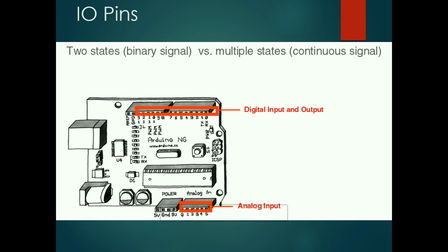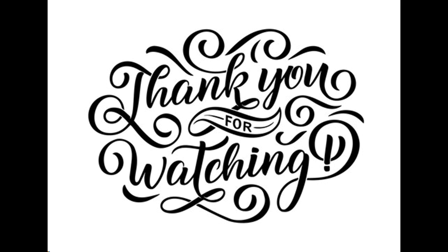Input and output pins were discussed before. Among the input and output pins, analog pins are only input. You can only give a signal as input, as analog can only accept input, but digital pins can be used as both input and output pins.